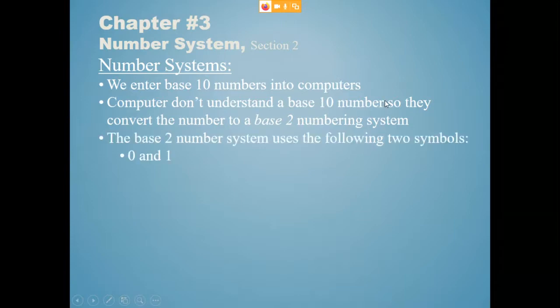They're binary computers, which means that they either have a 1 or a 0, and technically inside of that computer it's a voltage. We talked about that with the TTL logic voltage, 0 to 5 volts. Remember, with TTL, if you have between 2 to 5 volts, that's considered a high or a 1, and if you're below 0.8 volts, it's considered a 0.